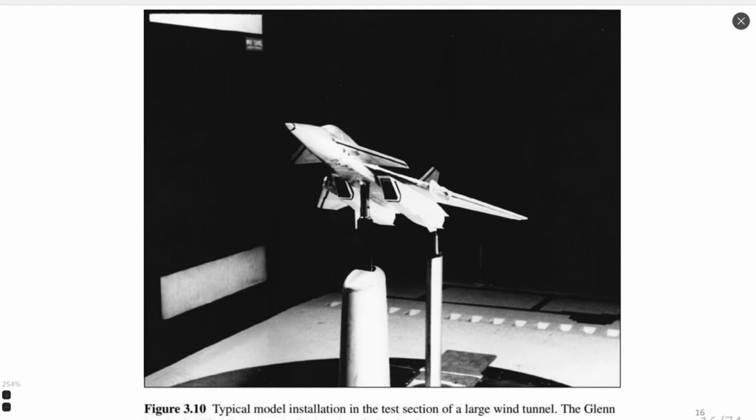If it's a streamlined body, it can be relatively big inside the tunnel, and can occupy maybe near 20% of the test section. And if this body is a blunt body, which has a big resistance to flow, it can be near 10% occupation, not more than 10%, especially for supersonic applications. The body should be small with respect to the area of the wind tunnel.